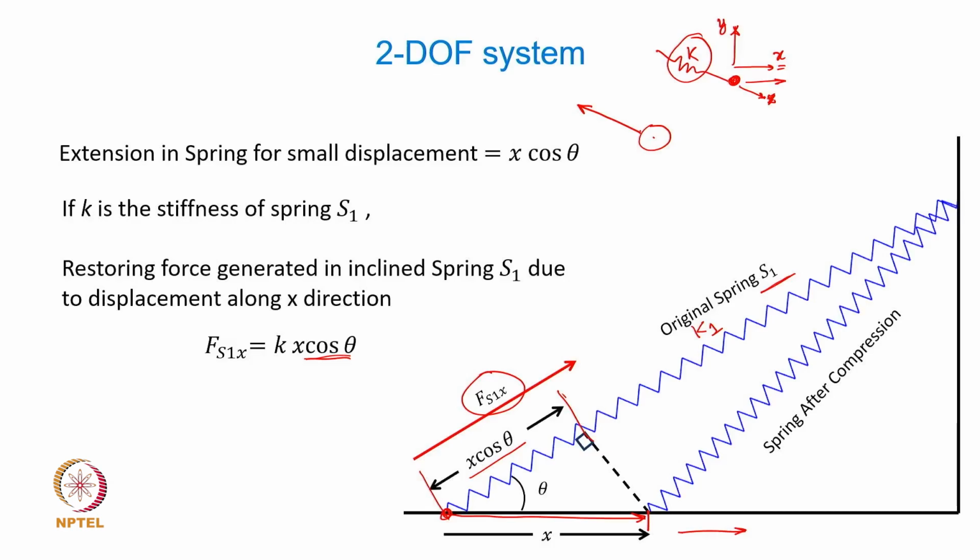If you look at a typical spring mass system, we have discussed this, that if the spring is at a certain inclination having its own stiffness k, then an equivalent spring mass system for the direction of motion along this turns out to be k equivalent equals k cos square theta, or alpha, whatever angle that you consider. This is angle theta, and you can show that by taking a component of this S1x along this direction.